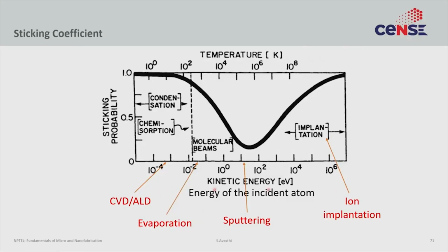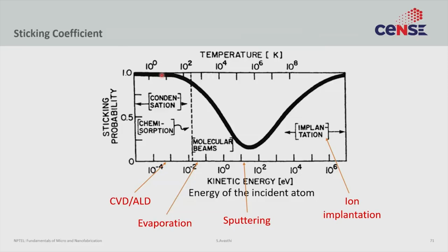And that actually has a huge bearing on the sticking probability. So stiction coefficient or sticking probability is one thing that I have till now in all the lectures assumed to be 1. Practically that is not the case, it actually changes. But to what extent does it change and under what conditions will it change is the subject of the slide. So it turns out the sticking coefficient is 1 under 2 extreme cases. Case number 1, if the incoming atom or ion or any material is at very low energies. So if it is coming very gently, then the stiction coefficient will be 1. The second option, if it is coming with an extremely high energy, the stiction coefficient is 1.